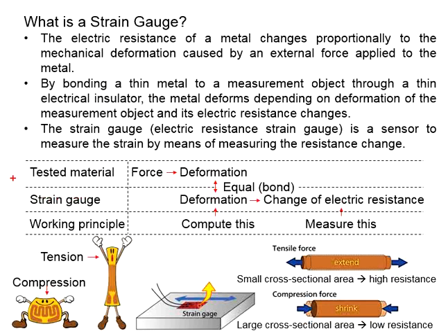Then we can adopt the strain gauge. The strain gauge is attached to the material. Make sure it is properly bonded and properly insulated. Now, if the material is properly bonded, the deformations of the material that you are testing should theoretically be the same as the deformations undergone by the strain gauge.